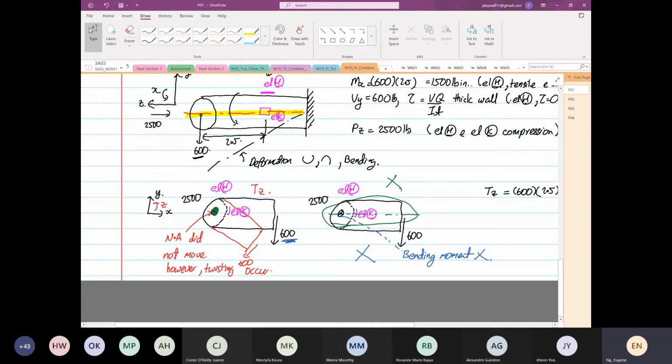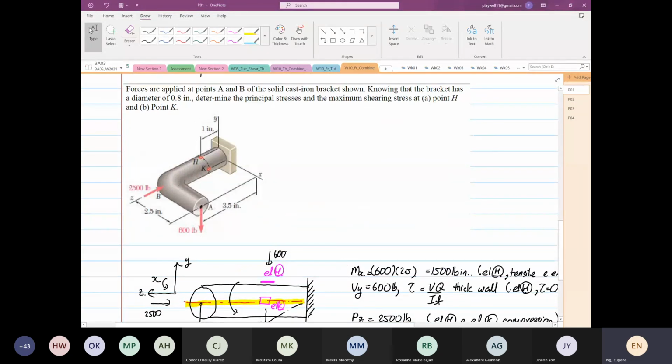So it causes both the shear force and bending moment for the 600. But it also causes a torque. Yes, if you view it from another view, it also generates a torque. Okay, so it can do three things. That's why it's important to look at the view. If I just look at this, I can't tell how many components or how many forces.